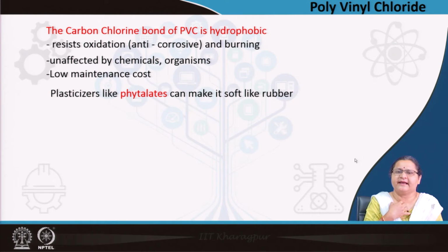Hence, it becomes a carrier of chemicals, it becomes a carrier of corrosive items, the sewer lines. The sewer lines, if it is metallic, it has acidic environment inside it and it gradually gets eaten away, gets corroded away by the soil it carries, which is not possible if it is PVC.